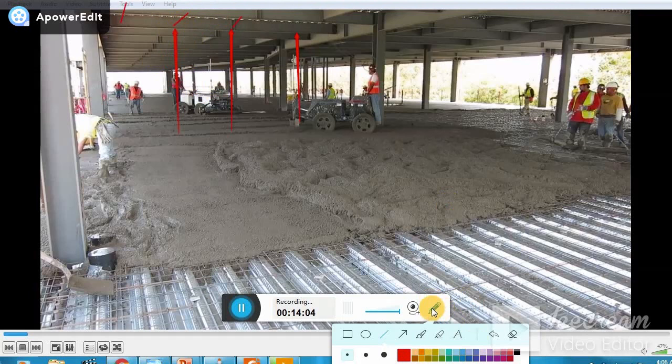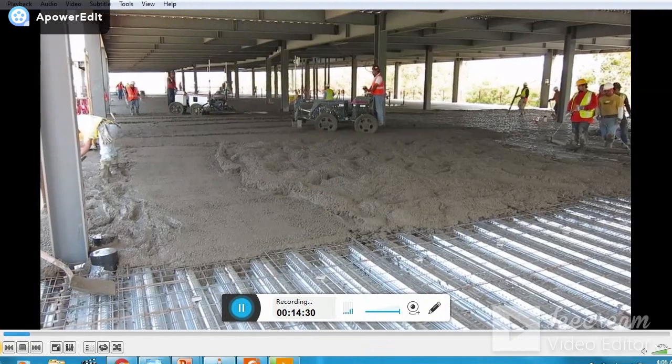Once we remove the shoring, then the combined action, or you can say the composite action, of the concrete and the beam takes the whole load. If we don't provide this kind of initial support to the flooring system at the initial stage, then the beams are responsible, as I already mentioned. So let us watch the rest of the video.